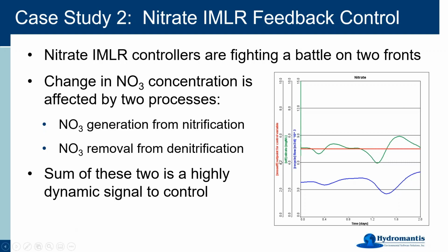And I just took the screenshot to illustrate that point. This is just 2 days of simulation here. And we can see this nitrate drops down, and then the recycle controller does respond accordingly, and it moves that down, and that comes back again. But here it drops again, and now it does exactly the same thing it was doing over here, but it didn't do anything. It keeps going down and down and down, and eventually it really drops right off. And then suddenly there's a big change.